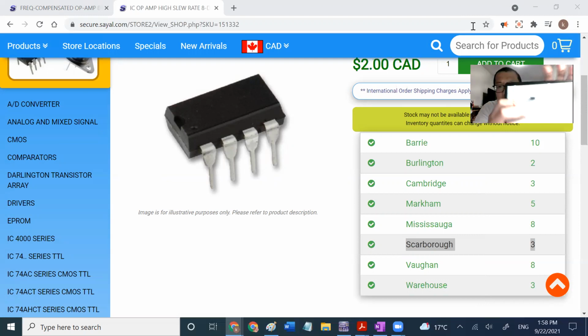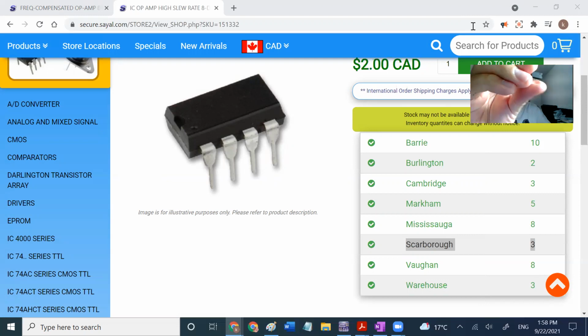When they connect it, they obviously know it. As you can see, there is a dot there. From the dot point, when you put the dot on this side, the upper one is pin 1, pin 2, pin 3, pin 4, and down goes back to here, 5, 6, 7, 8.